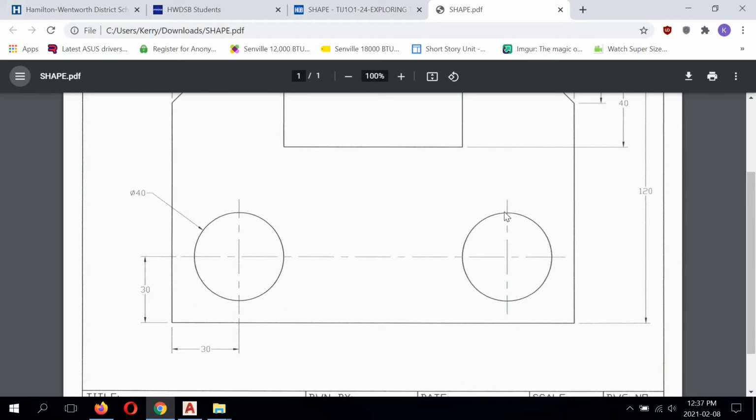These lines here are called center lines, and they are lighter in contrast, and they're not actually a part of what's being created. This is a drawing standard or a drafting standard for mechanical drawings. So a center line has to be added to any circles on a drawing, and they should be added to identify features that can be lined up, and also identify symmetrical features on a drawing. All right. And they also stick out a bit, right?